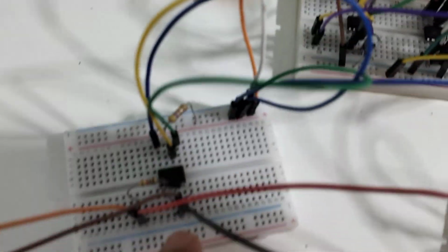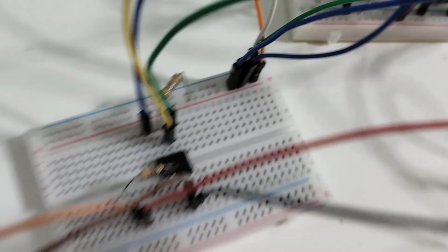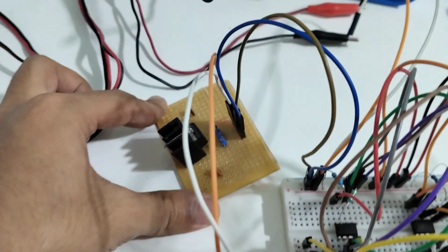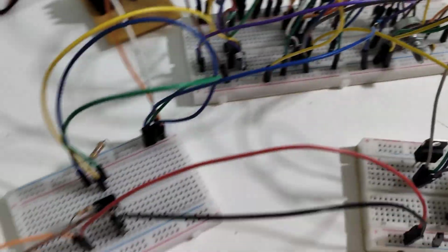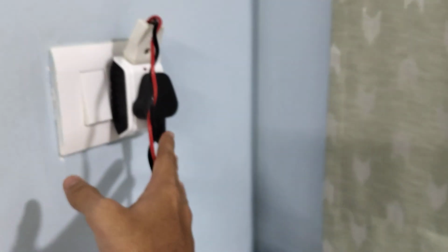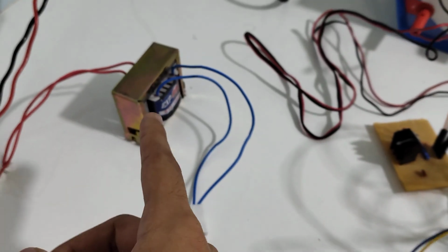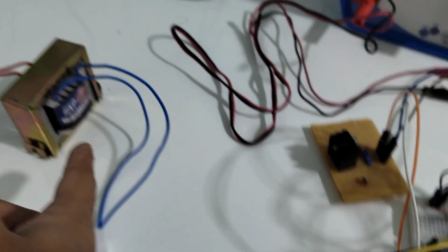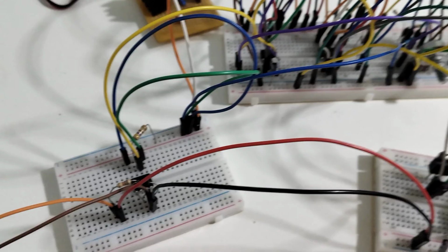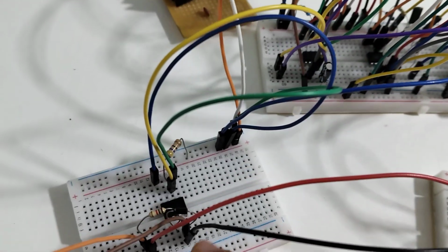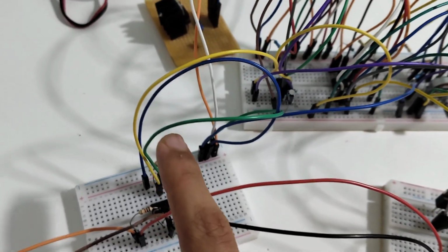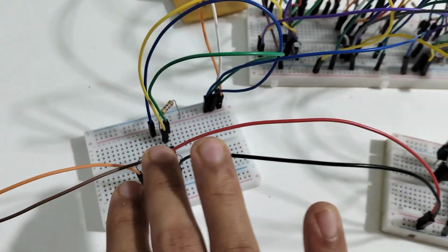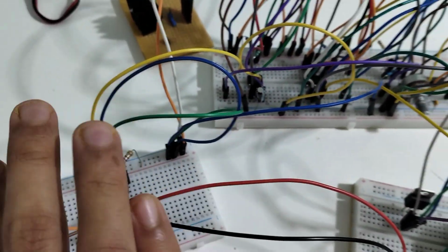And the logic level optocoupler, I said you cannot give 12 volts to this. This runs on 5 volts, so a small 7805 here. So starting with the transformer, we have the AC connection of the grid here, and the transformer which is going to step it down to 15 volts or 14, whatever. And there's the optocoupler, and this is our other side. So now this AC side is isolated from this, so it's protected.